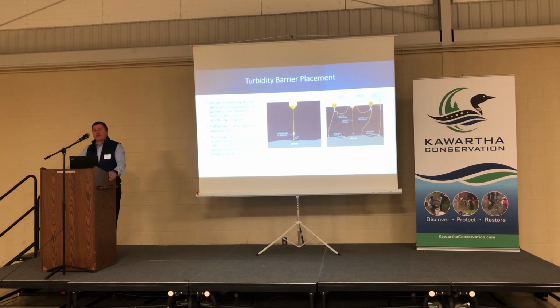So proper installation is also really important in how these curtains are hung. One of the regular questions that we get is, should the curtain extend vertically all the way to the bottom? The answer to that is no. Our goal is to keep about 12 inches, 300 millimeters, from the bottom of the water body to the ballast. So the idea is for that curtain to be able to float back and forth.